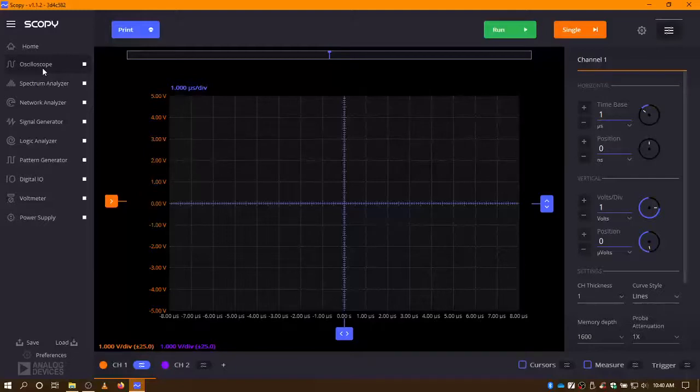So for a 25 megahertz scope, you would probably be able to read 7 megahertz in. What that mainly means is if you were to look at a 7 megahertz signal, once you get to that point, it should be down by 3 dB. In other words, if it was a 1 volt RMS signal, it would be down to about 0.707 RMS.